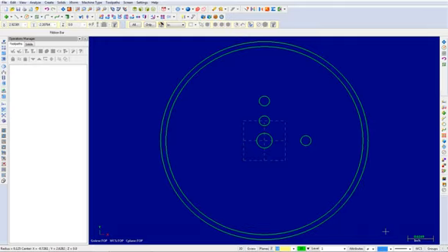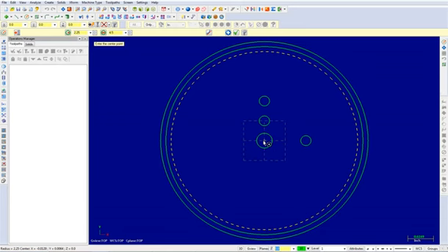Next, choose the Create Circle Center Point command. From here, click on the diameter icon to unlock the value. Now enter a diameter of 4.5 and choose the origin. Once complete, choose the OK button to exit the command. Your geometry will appear as shown up to this point.